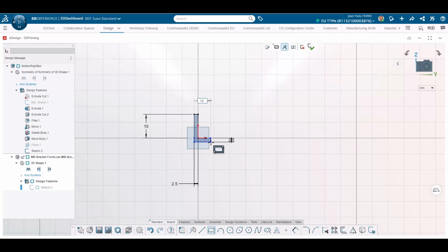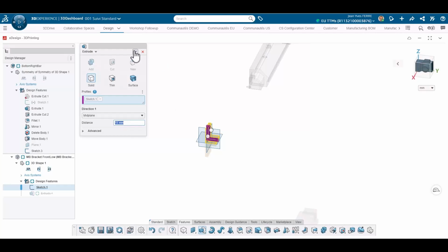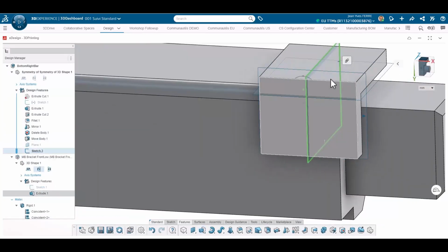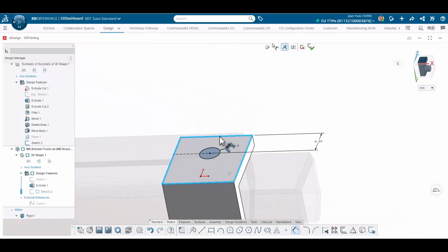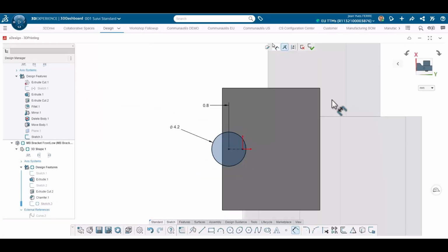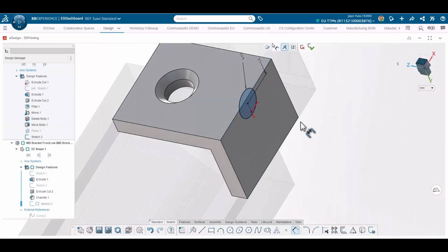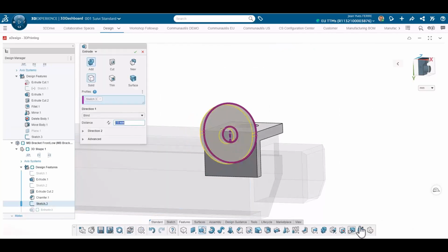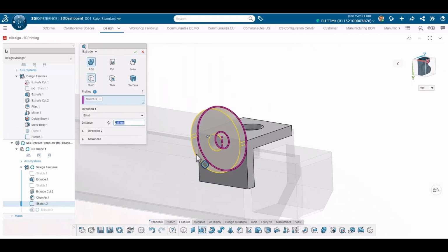They will be fixed on the bar at one side and on the motherboard on the other side. So I need to add material between bar and motherboard. It will be an extrusion with a hole to fix to the bar, and a boss with enough material around the mounting hole. Dimension between motherboard and bars is 5 mm. So 2.5 mm for extrusion thickness and 2.5 mm for the boss.